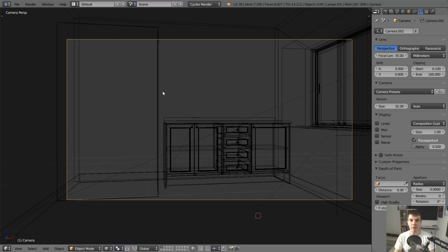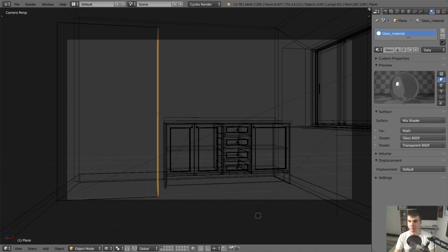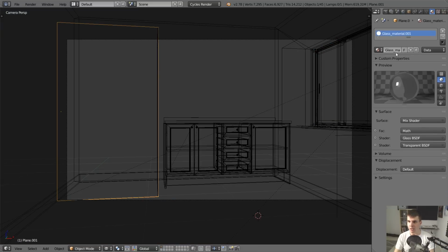To add a little bit of visual interest, I'm going to make the glass have, like when you look at a glass door side on, the thickness of it has that sort of dark aqua color to it. So we can do that in Blender. First of all, let's make it a separate material so that we don't apply it to our glass over there. So I'm just going to click the little number next to it, and let's call it glass shower.